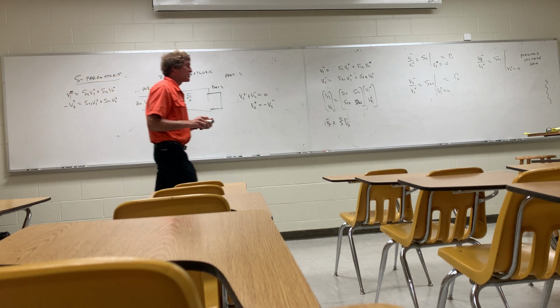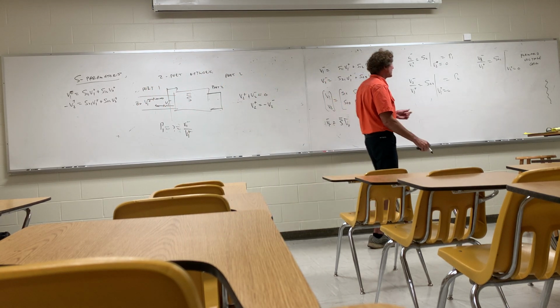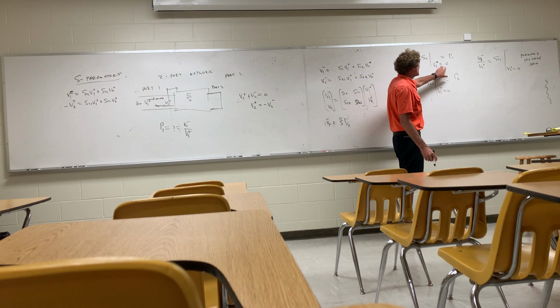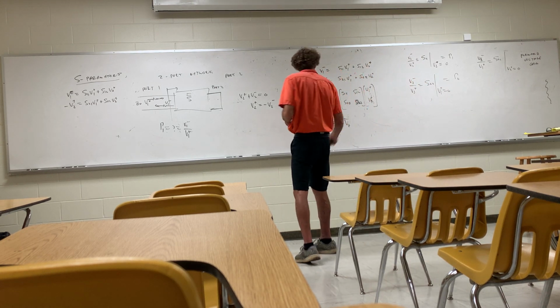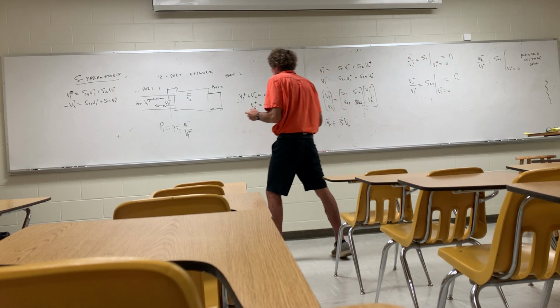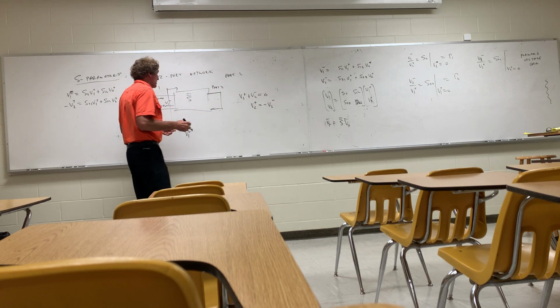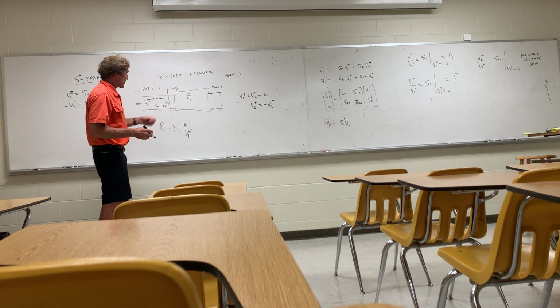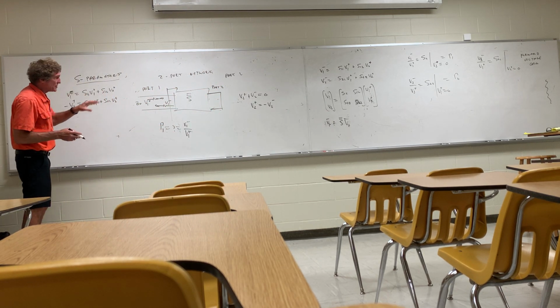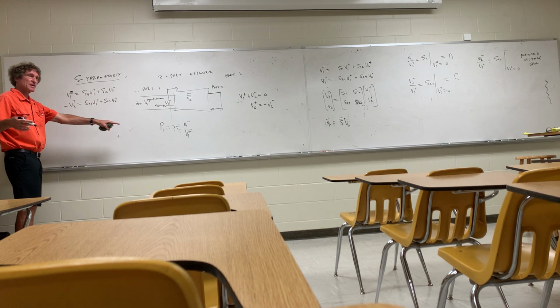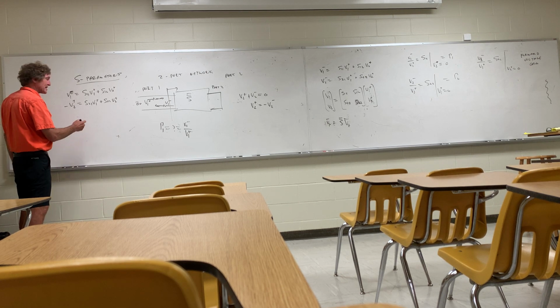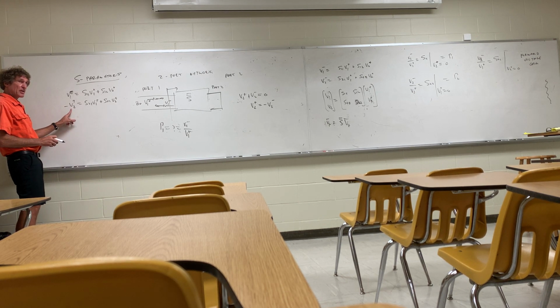When I have the reflection coefficient over here, V2 plus, that would be when this is actually preventing any signal from ricocheting back, then you get the reflection coefficient of that port. And when that is the case, we get S11. Here, we're assuming we know the S parameters. So we're going to assume we know the S parameters, we just short the port when we want to get that reflection coefficient. I should have said that a little clearer to start with. All right, now take a look at this. Y'all follow me right here?